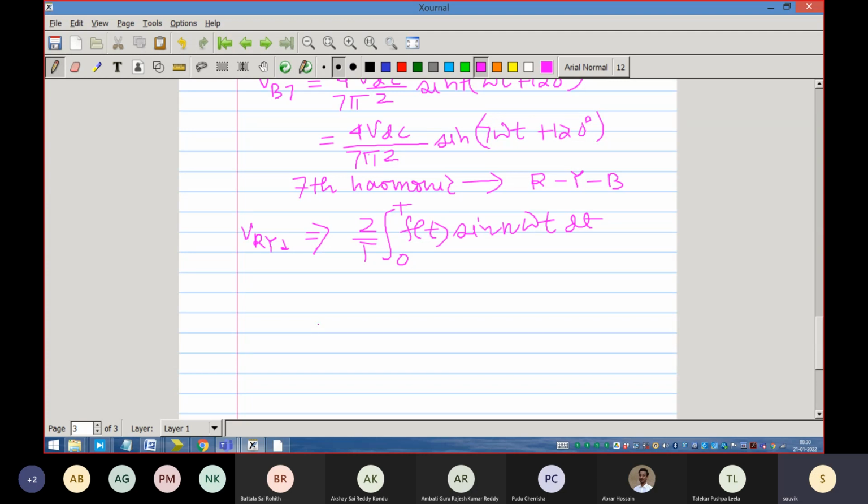So if we look at it, this waveform we will be integrating from what point to what point? For the fundamental component, because 0 is shifted, we will be integrating only between 30 degree and 90 degree. That is the angle we will be integrating, because after that it is just an identical thing, and 4 times that.